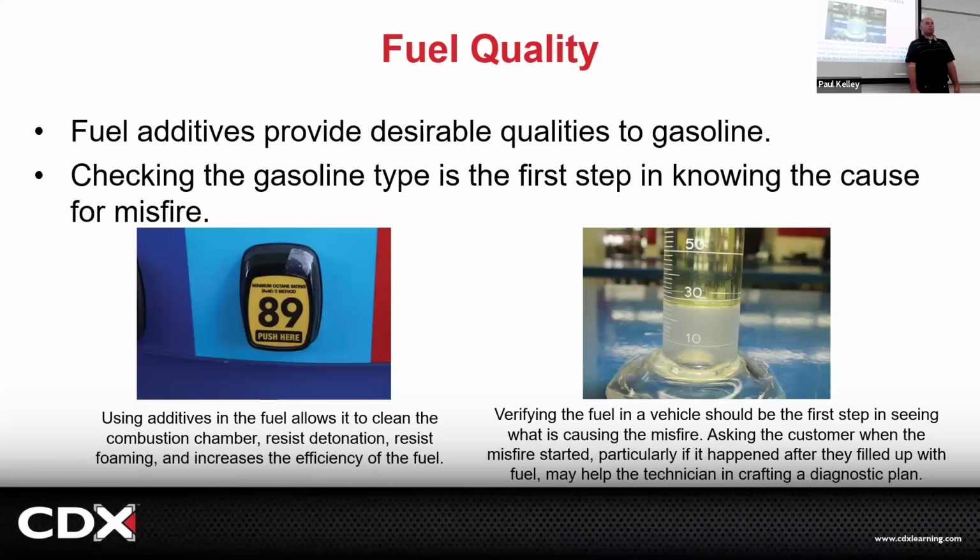And they'd be like, what the heck is that? Google it. Google was kind of new, right? But if they found a place that had a top tier fuel, honestly, it would resolve their issues a lot of the time. It's pretty gnarly. But wait a minute, this is 86. You're telling me I need 91? No, not the octane. A top tier fuel is a different additive package, and it would actually resolve some things.